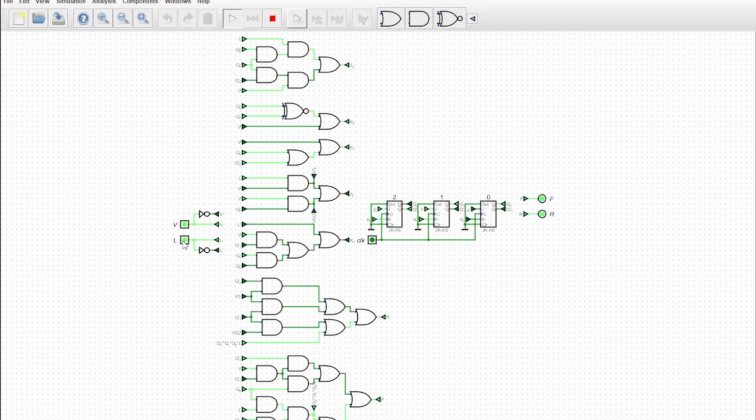That was an assumption I made, because if the pool is very low, your other sensor is also going to be very low, unless the sensors are broken. So if V is ever on and L is not, then your sensor is broken. V should not be on. And that was an assumption I made, and so that is just another failsafe. So this also checks, is V working properly? If not, then we're just not going to run it. It will just never run. And so yeah, that was the design.